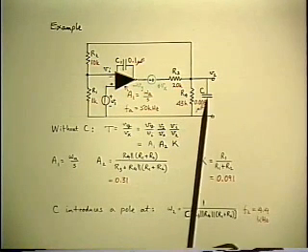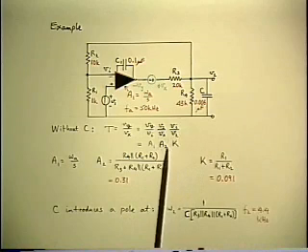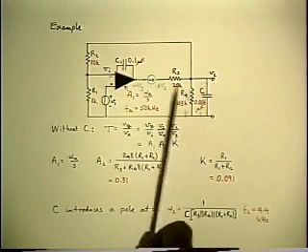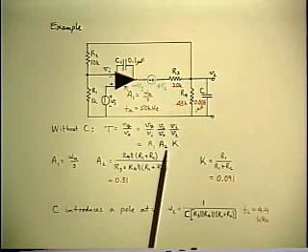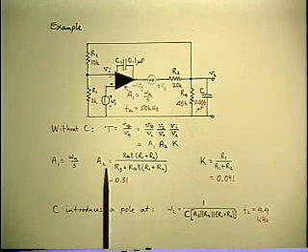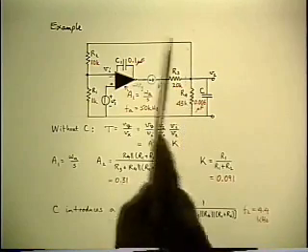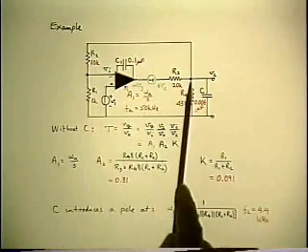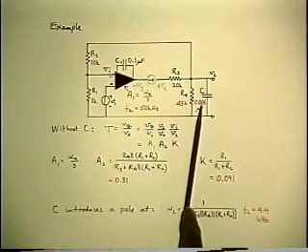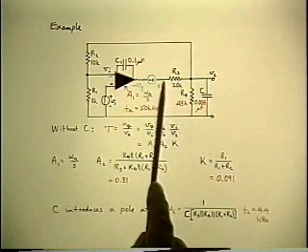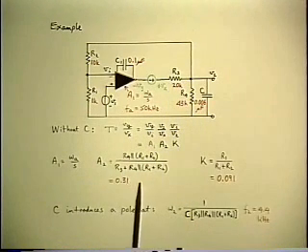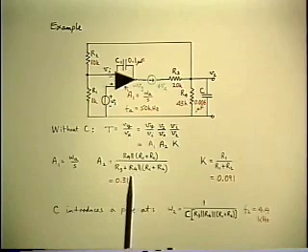So if at first I leave it out, then the factor V2 over Vx is a simple resistive divider, so I've called it A2. And the A2 is R4 parallel R1 plus R2 is the bottom branch, and the denominator is the same thing plus the top branch, which is the R3, and that factor is 0.31.